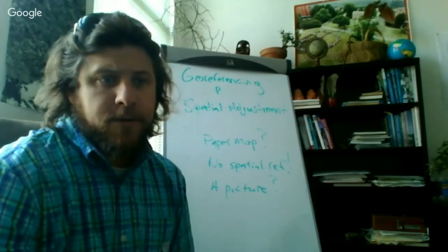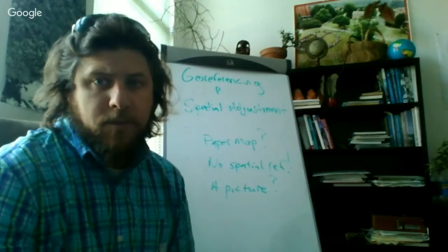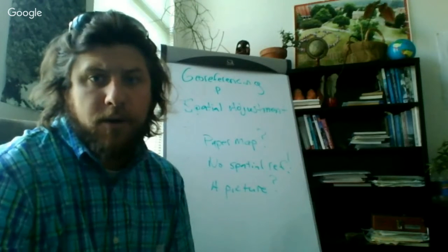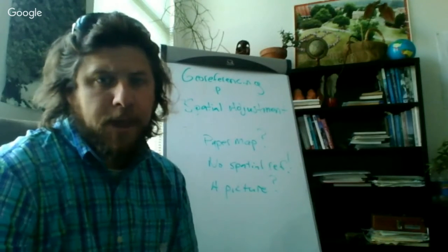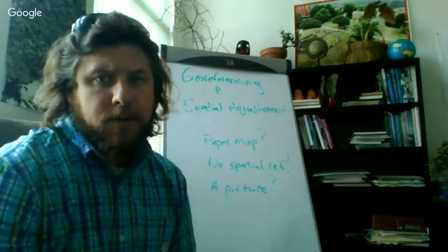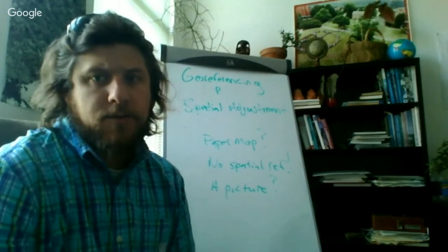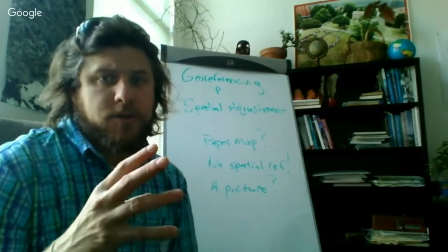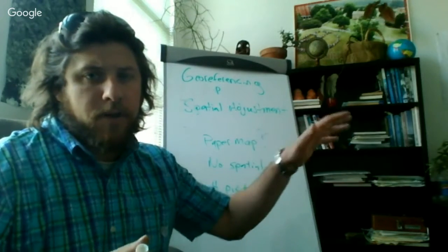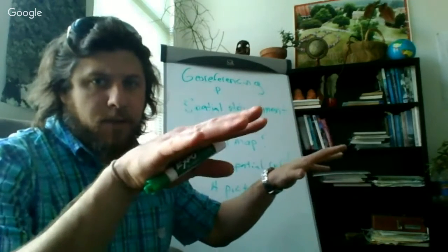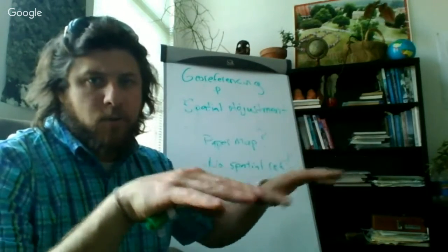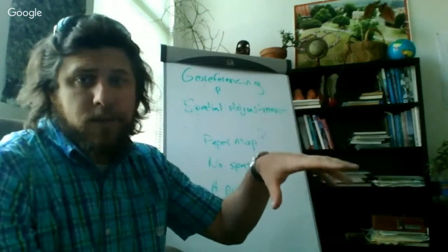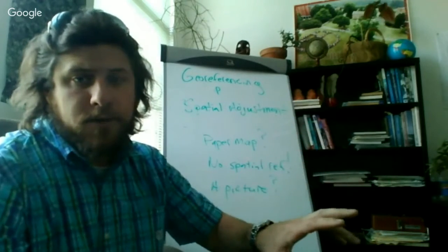It's one that has been picked for some reason, maybe because we want to retain properties of distance or shape or area or direction. And when we conduct a correct spatial analysis, as you should know, we always make sure to match projections. So if we have a layer that's in UTM and a layer that's in state plane, we've got to pick one or the other to project so that everything in our table of contents is in the same coordinate system and also in the same projection.